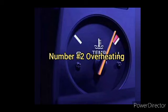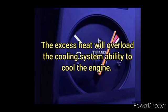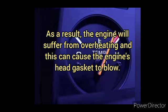Number 2. Overheating. When the exhaust system is blocked, hot exhaust fumes will be backed up into the engine. The excess heat will overload the cooling system's ability to cool the engine. As a result, the engine will suffer from overheating and this can cause the engine's head gasket to blow.